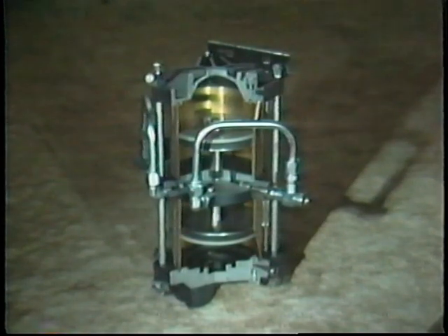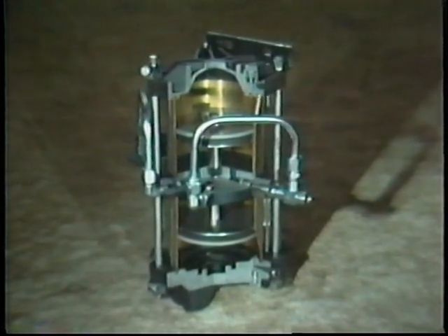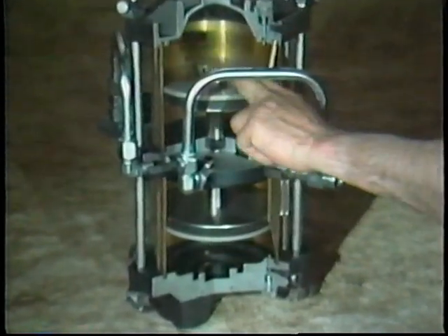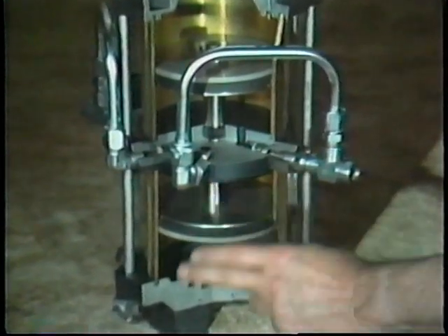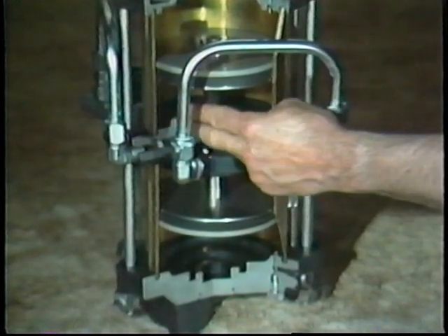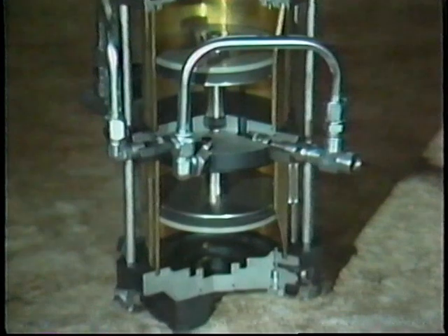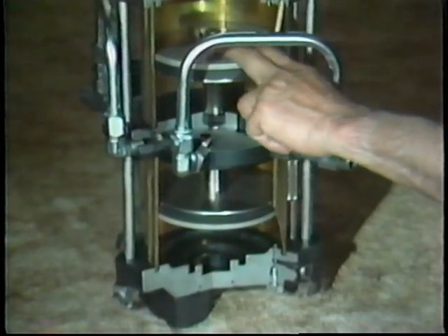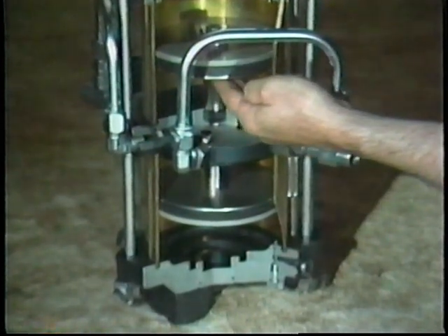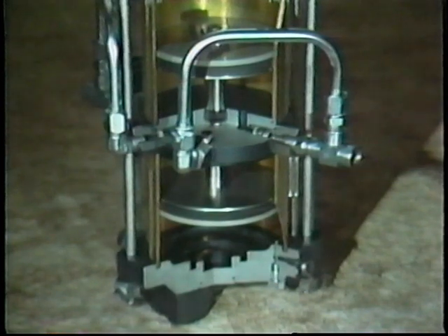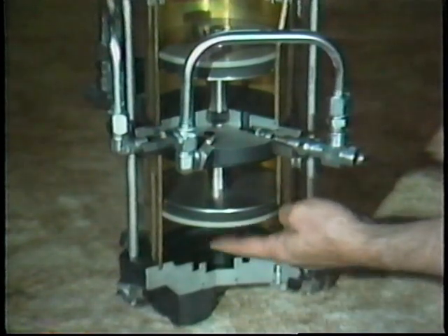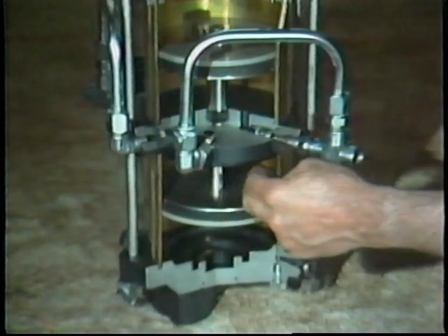Here's an interesting 2-to-1 booster, which at least one manufacturer markets. As you can see, it uses 2 pistons that are the same size. But by allowing primary air pressure to the top side of both pistons and venting this chamber, they are able to get a 2-to-1 pressure increase in this chamber. Why? Because the combined piston areas here and here on the primary side are double the area here on the output side. On the return stroke, the flow paths are reversed. Primary pressure is applied to the bottom of both pistons, and this area becomes the high-pressure chamber.